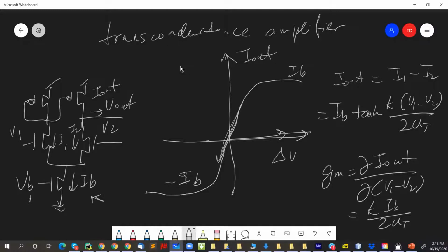And also remember, if you operate this in subthreshold, then you're going to stay within some fixed region over here, right? Remember, because the transistors in subthreshold saturate around 100 millivolts. Which means now if I change IB, but this IB current still ensures that the circuit stays in subthreshold, so let me say I change it to IB2, then you're going to saturate at a similar place, okay? So this region over here is approximately about the same.